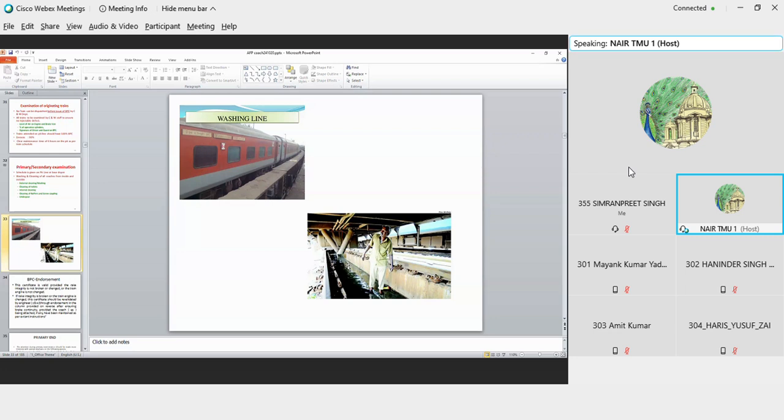So that is called terminal attention or platform attention. And there is a gap of 2 or 4 hours only which is available. When the rake is kept on the platform only, interior cleaning is done and a brake continuity test is done. Again, the CNW fellows will come. They will see whether the brake cylinders are in working condition or not. So this is called terminal attention.